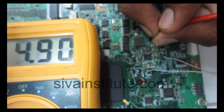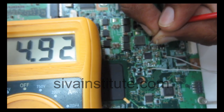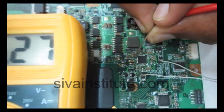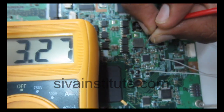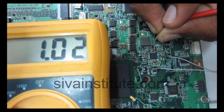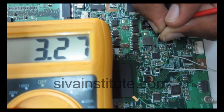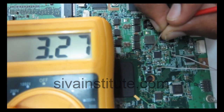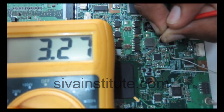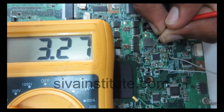4.9 volts. So 5 volts is OK. Next, 3.3 volts. See here, 3.27. That means 3.3 volts, so the first step is OK. When you first connect the adapter or battery, you should check here at the 5 volts and 3.3 volts regulator IC. This is the 5 volts and 3.3 volts regulator IC. Whether this is OK or not, you should check here.